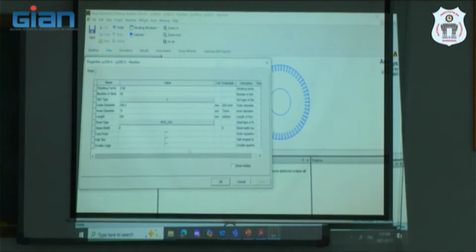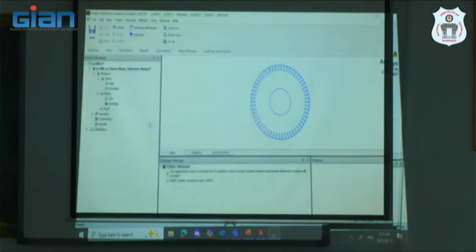In the student version, there is a bug. So if you go into rotor window and if you click on the material type of the steel, the software will crash. So don't do that. It's just a bug in the student version of this 2024 release. Latest is 2024 release. Just in 2024 release they have this bug. So when they release the next version, they will fix it. I mean, the reason why I'm saying that is otherwise people have built it from scratch, but anyways.